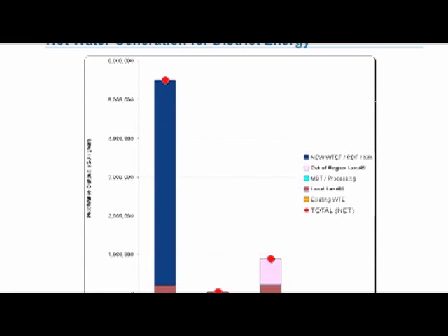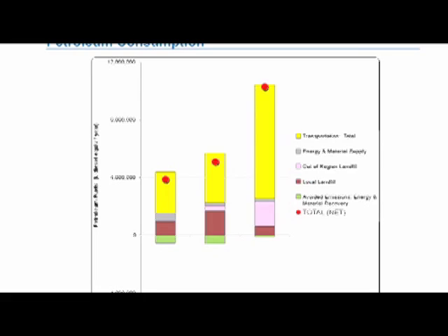Hot water generation, this is the district energy. This is what makes waste-to-energy actually very efficient, and it takes it from 27% efficiency to over 90% efficiency. And you can see that there's a lot of hot water in terms of the heat that is extracted from a waste-to-energy plant as compared to a landfill, where we also burn the landfill gas for power and extract the heat for district heating, but it's just not nearly as much. And of course, on the MBT, because we don't extract any energy, there's not much to be had.